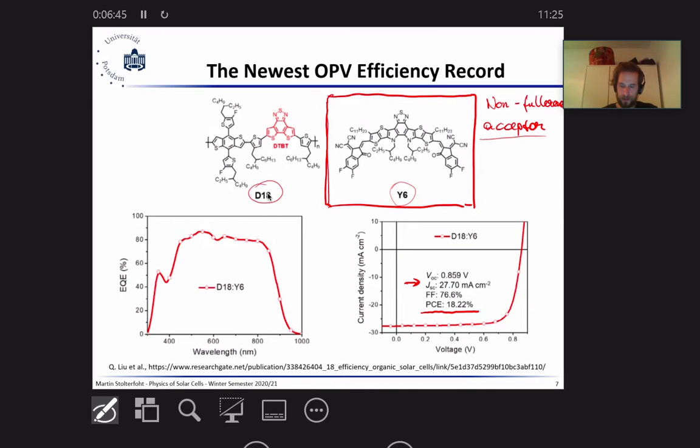The band gap is usually around 1.4 eV now, so it's in an optimum regime of the Shockley-Queisser model. So notice the low band gap here, depending how you see it. Compared to silicon, it's of course a high band gap. Compared to perovskites, it's quite a low band gap, except for tin perovskites.